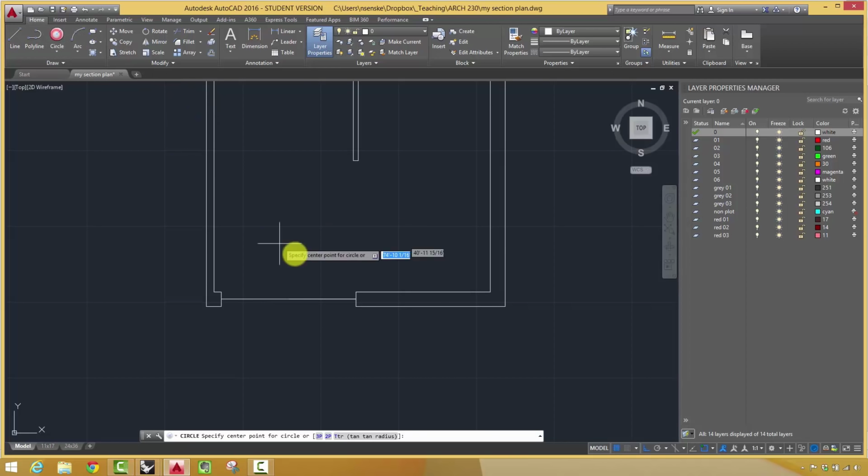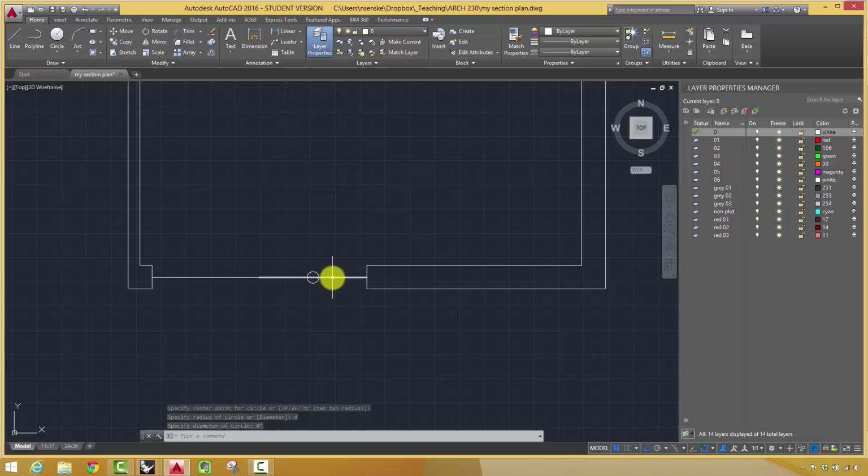Okay, so I'm going to make a circle there, which is going to be my pivot. And if this is a foot, then I want to do diameter D of 6 inches, and that will give me that. Okay, and I'm going to go ahead and delete this line. Just press delete. Now I've got this piece, and I can offset it 3 inches in each direction. Okay, delete this, and then I'm going to go ahead and make this a rectangle. So I'm just tracing over this.